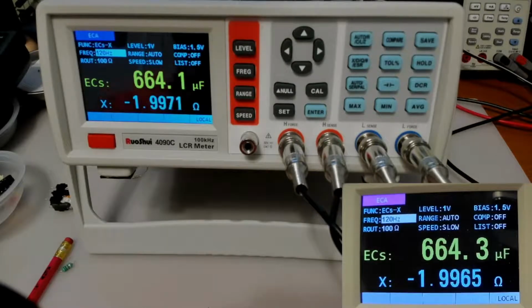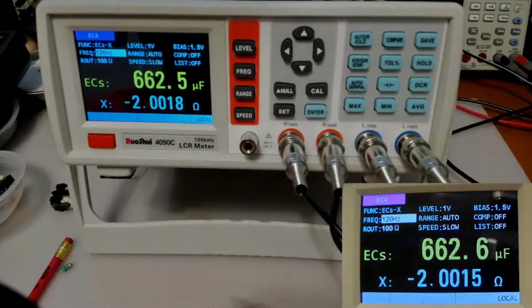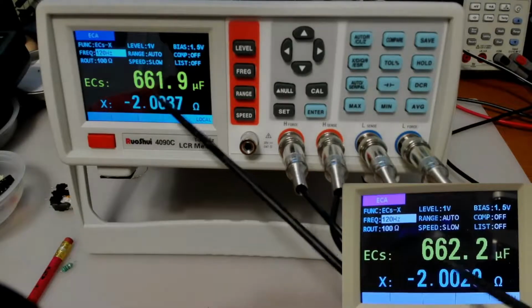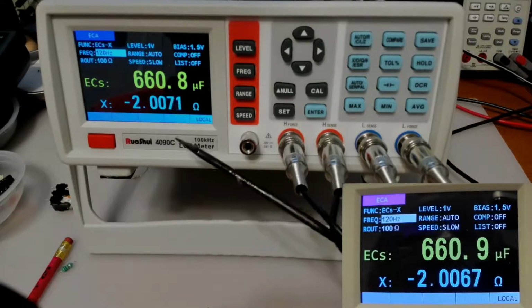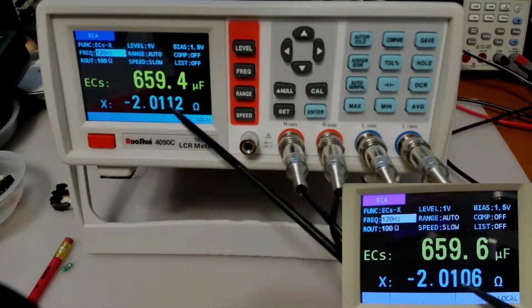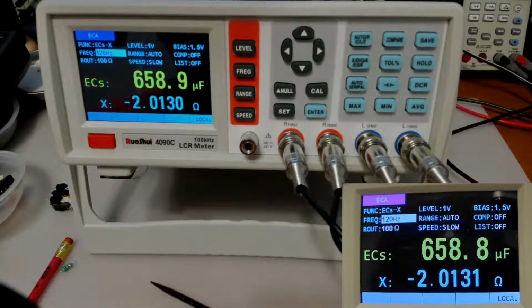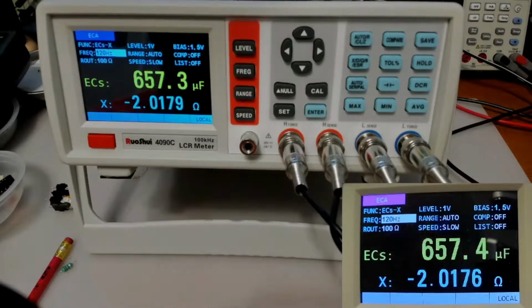And this is actually a bad electrolytic capacitor, a known bad one. It is marked at 1500 microfarads at 6.3 volts, but as you can see, it has 662 microfarads, and in fact it varies. Sometimes when you hook it up, it'll be less. It has a very high ESR, and we've got it set to 220 hertz, which is appropriate for those electrolytic capacitors.